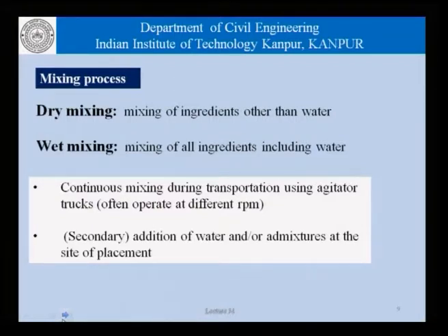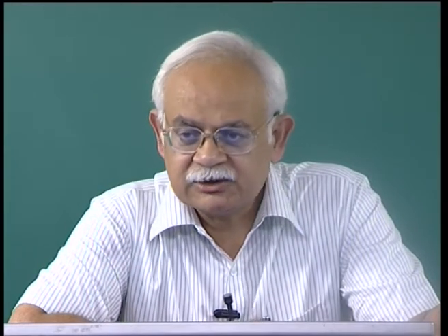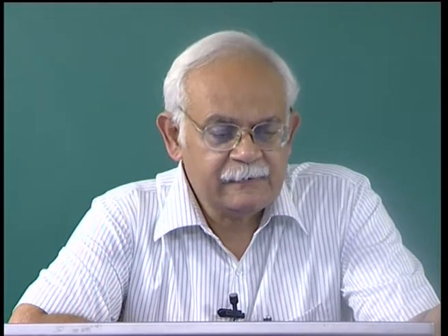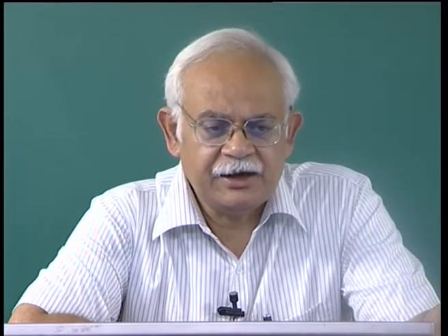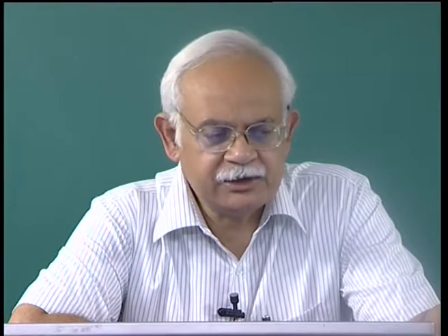That is, it will be gradually mixed while it is being transported, but once the concrete agitator truck reaches the concrete placement site, it will be vigorously mixed for a period of say 15 seconds or 30 seconds in order to ensure that if at all there has been a problem during the gradual mixing process or the agitation process, that is taken care of by this vigorous mixing.